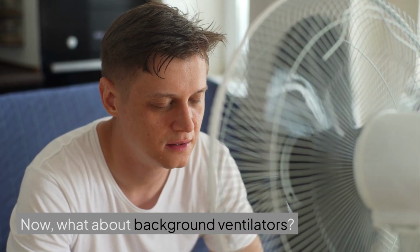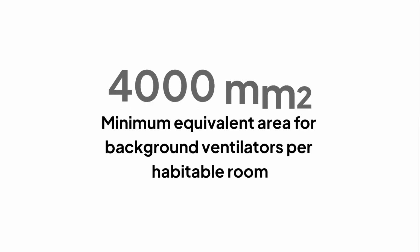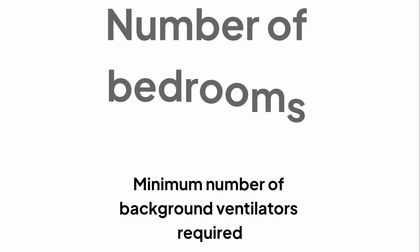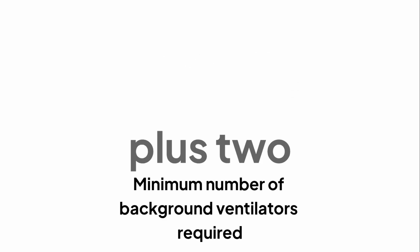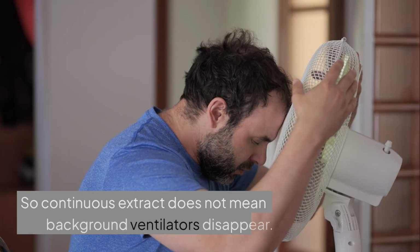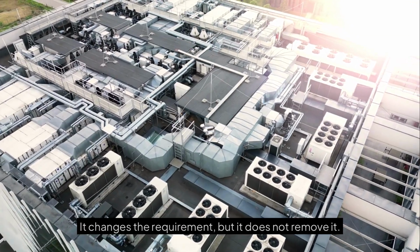Now, what about background ventilators? This is another area people get wrong. Paragraph 1.64 says that where continuous mechanical extract ventilation is used, background ventilators should not be in wet rooms, but they should still provide a minimum equivalent area of 4,000 square millimeters for each habitable room in the dwelling. It also gives a minimum number of ventilators equal to the number of bedrooms plus 2. So continuous extract does not mean background ventilators disappear. It changes the requirement, but it does not remove it.